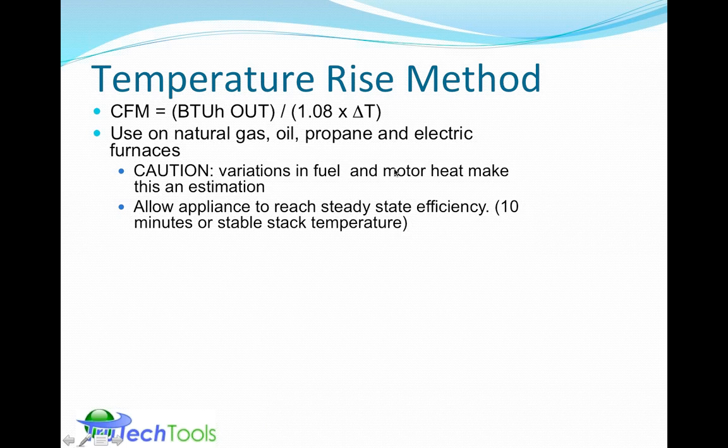For the fuel oil type, or gas oil and propane type. For electric furnaces, it's a little bit easier because you can actually just change kilowatts into BTUs per hour output and then do that calculation correctly. Still paying attention, though, to the motor heat.